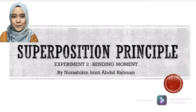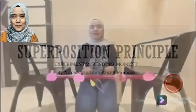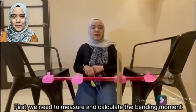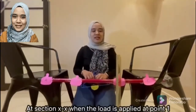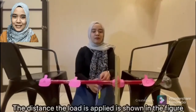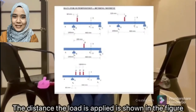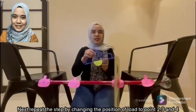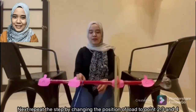Superposition principle, experiment 2, bending moment. For the superposition principle, first, we need to measure and calculate the bending moment at section XX when the load is applied at point 1. The distance at which the load is applied is shown in the figure. Next, repeat the step by changing the position of the load to points 2, 3, and 4.